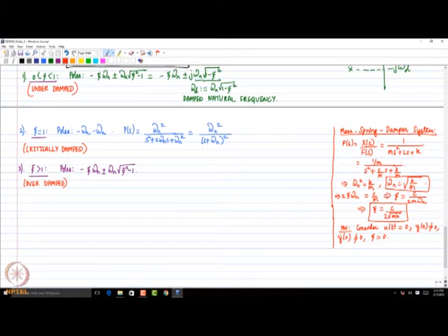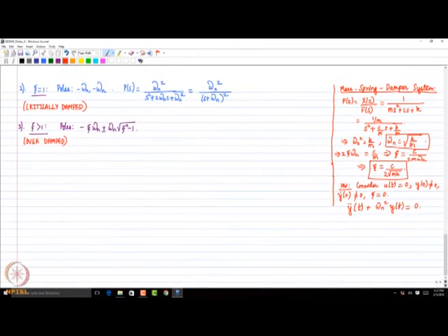Okay. So what is the system that we are dealing with? Y double dot t plus omega n square y t equals 0. Apply the Laplace transform. Of course, now we need to be a bit careful, because the initial conditions are not 0. And calculate the free response. Then you will immediately get the answer.